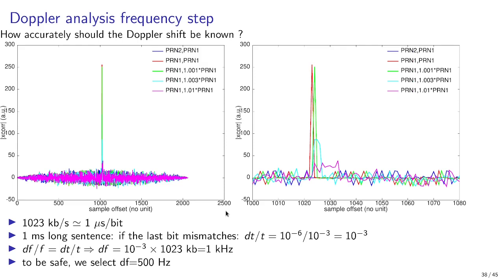It is reasonable to try to search frequency steps of a few hundred hertz to minimize the computational load and yet allow for the energy to accumulate without spreading the information if the carrier frequency has not been properly compensated for. Furthermore, the data rate must be adjusted to tune to the downlink data rate.